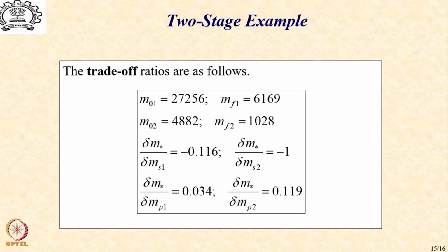And now you will realize that most launch vehicles try to use a higher ISP fuel in the higher stage, and now you will understand why. Why do you not use solid propellant in the higher stages? Because it's a lower ISP fuel. It will give you a lower efficiency of the stage, so that in case you want to do a trade-off, it is not going to be a very efficient design.